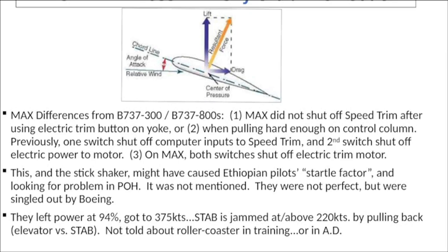So it's jammed now. Then you put the nose down again, once you gain some altitude, just like you're on a roller coaster, up and down. And this was taken out of the manual after the 200. And this is also not mentioned in the Airworthiness Directive that came out after the first accident in 2018.